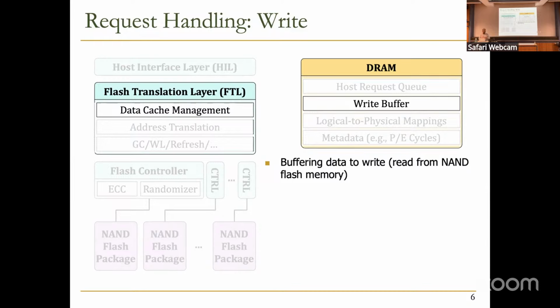So in order to make sure that this device is persistent, that's one of the criteria that it has. And that's actually one of the reasons that they cannot make that DRAM buffer large enough. They cannot make it larger and larger, because if they make it larger and larger, they need to add more capacitors as well. And they will come at the price of scalability, essentially.